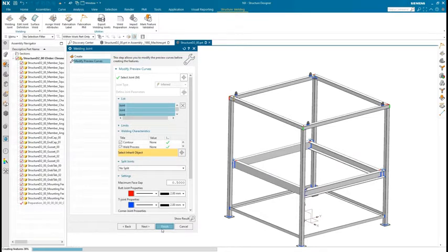An actual weld feature is created, but not the physical weld. In a design such as this, physical beads are rarely needed. Beads can be added later. The curve for each weld is created and can be used in a robotic welding process. The advantage of creating weld features is being able to add PMI.